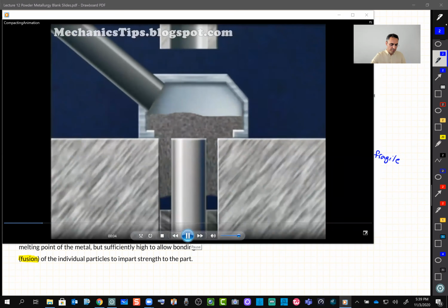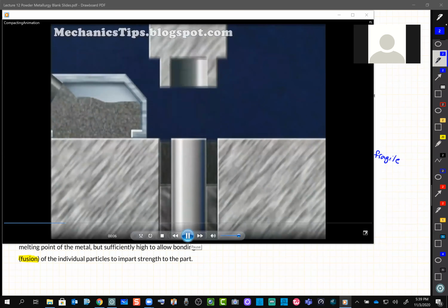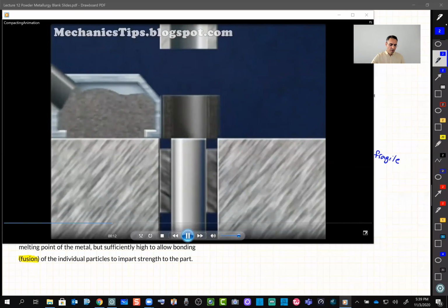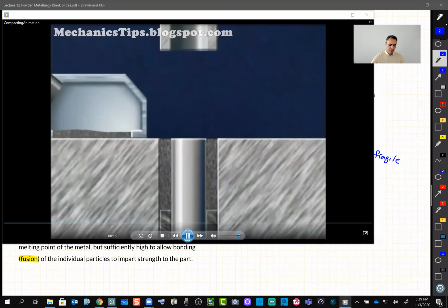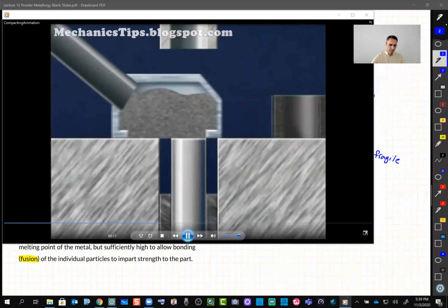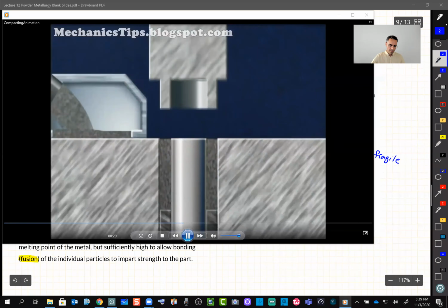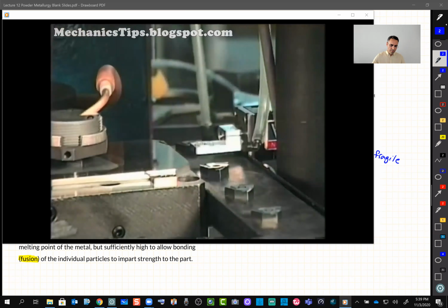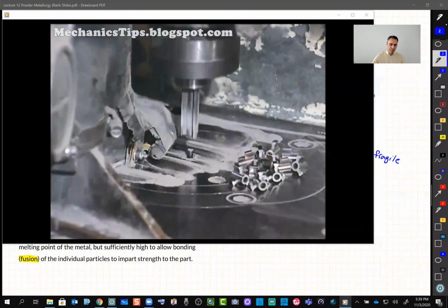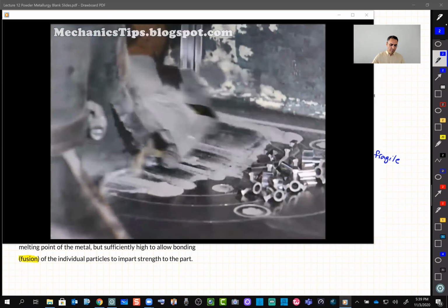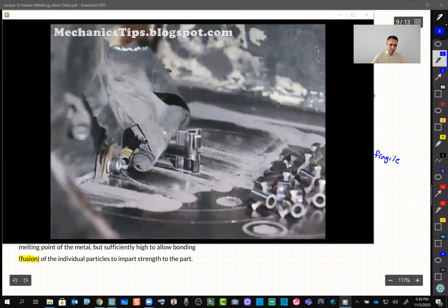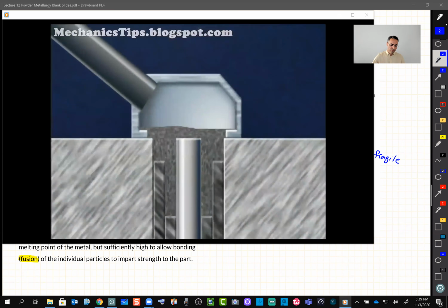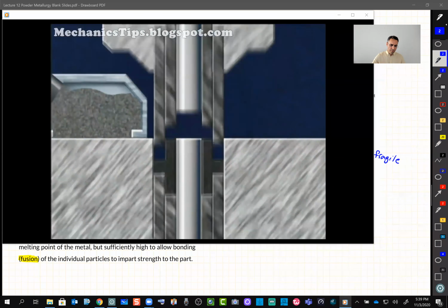The powder can be pressed from one side by the upper punch. When that punch withdraws, a lower punch raises the part out of the die. The part is then ejected by the wiping action of the powder feed chute, which also wipes powder for the next piece into the die. Ejection from the press can also be accomplished using automated handling equipment. The density of pressed powder tends to decrease along part height as the distance between the compacting punch and die increases. To produce more uniform density, thick parts are compacted by a set of upper and lower punches.